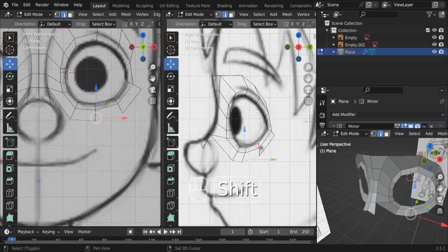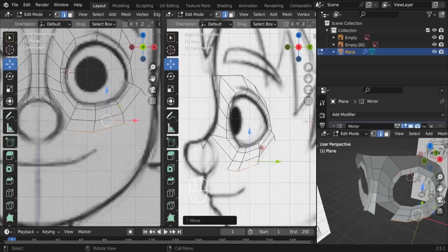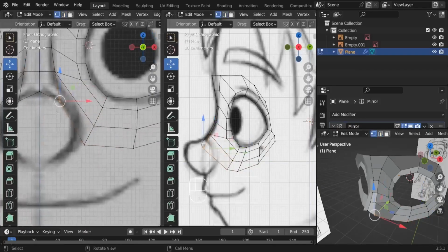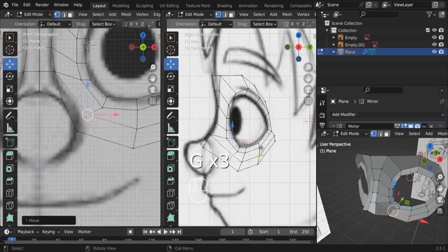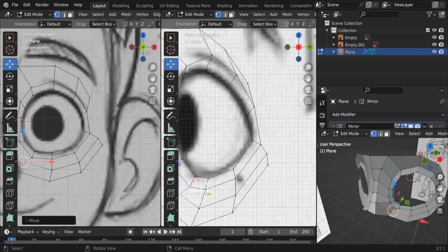And we can add an additional loop. So let's select these 3 edges. We can extrude them down, scale them again a little bit up, push them outside, and we can grab these 3 edges and press F to fill them. Perfect. Here let's do some better alignment. Pretty much good.